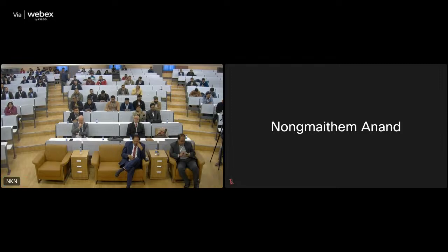Now, as the background work, you might have seen the work carried out by Barton, on what will be the effect of pre-grouting in the improvement of the rock mass quality Q. So grout material percolates through the cracks, joints and fractures, these fractures can be during the tunnel blasting, the excavated damaged zone, which can be around 1 meter around the tunnel opening, and it may be more if you have uncontrolled blasting. So Barton et al.